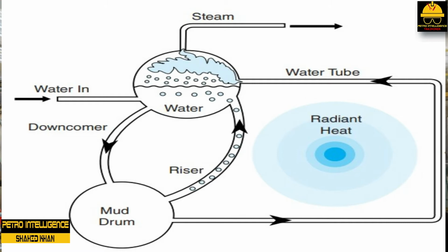This circulation rate can easily reach 2 million pounds per hour. At this point, approximately 65,000 pounds per hour of steam is being produced. Each time the water passes through the tubes, it picks up more heat energy. When the pressure increases to slightly above the system pressure, steam will flow through the non-return valve into the system. Boiler load is a term used to describe the plant's demand for steam.